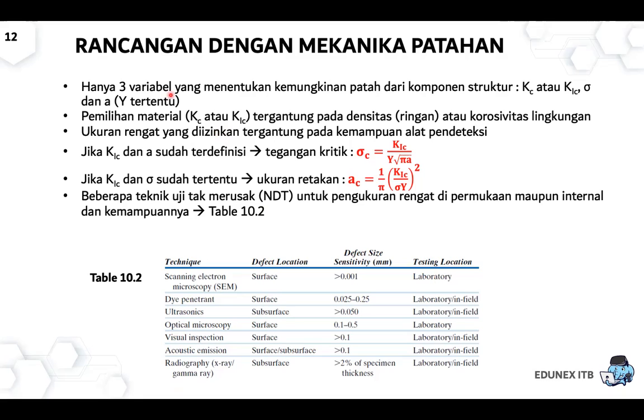Okay, so when we do the design, if we have a K1C, we know the metal, we know how much A is defined. For example, I have this reactor and I found that the A, or the crack, is actually 3 millimeter. How can it stand this load? So your critical stress would be this one.